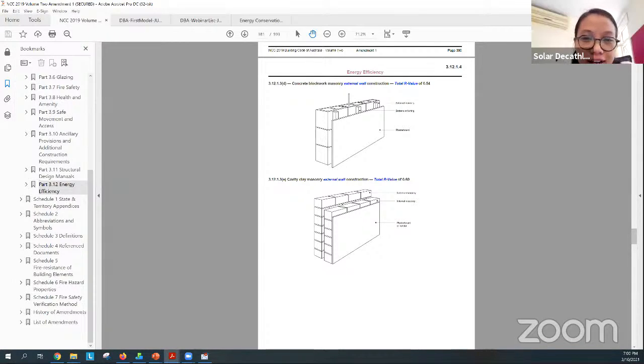Yeah, and I guess within Design Builder, you just model the layers. So you can have an air layer if there is a cavity. Depending on whether that is a vented air layer or a still air layer, you need to pick the right R value. That's the thing to watch out for.